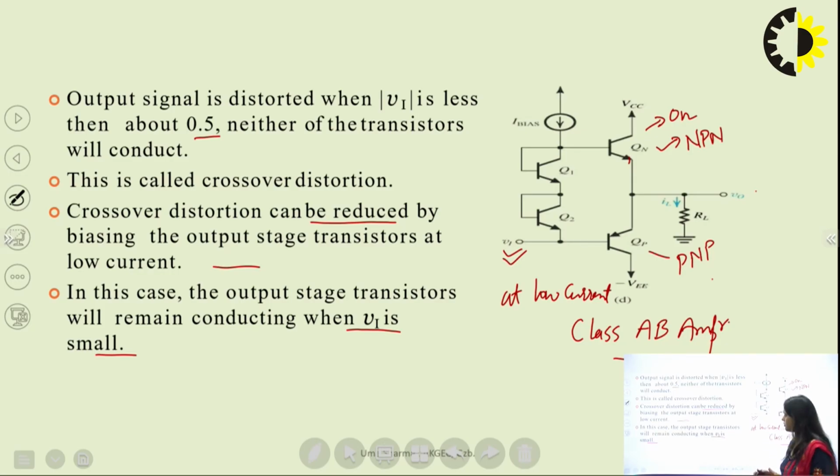When we are talking about the biasing circuit, these circuits are responsible to bias the different stages like input stage, gain stage and the output stage. And biasing circuits consist of different current mirrors like simple current mirrors and Widlar current source. Then we have discussed the input stage. Input stage is basically a differential amplifier stage, and with the help of the differential amplifier we can reduce the effect of noise. This is the beauty of the operational amplifier: when we apply the input at positive as well as negative terminals, the noise can be eliminated, because the effect of noise will be on both the terminals. So we can nullify the noise effect.